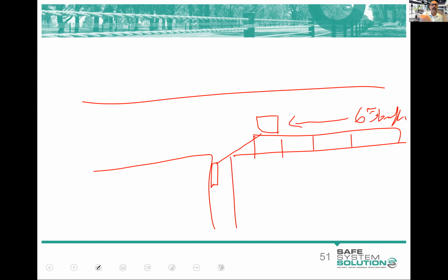That is what we will write up as our issue. The parking spot creates a sightline impediment for the vehicle exiting. This could result in a vehicle exiting the road being struck by a vehicle coming through, and there are some risk factors that increase that, and you risk rate it, whatever it is. Then you make your recommendation or your recommendations.